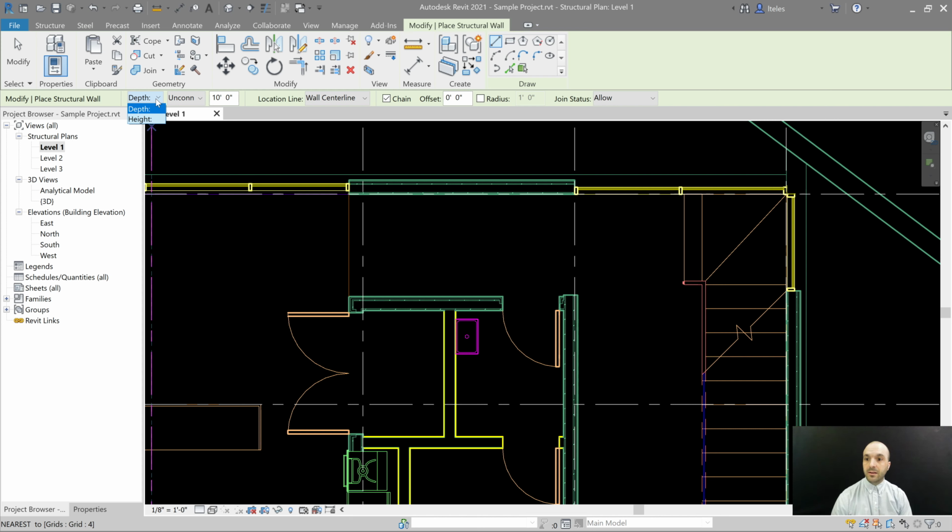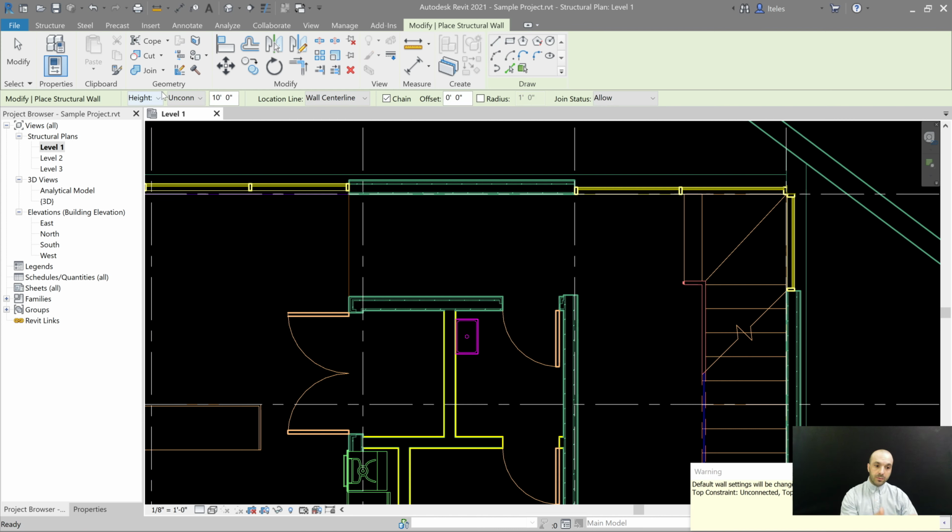Fight the habit of not going through these options, okay? So let's go through these and tell Revit, we're communicating with Revit and saying, no, we want it to go up. Revit tells you got to reset and keep going with your options. And the next option over, we tell Revit, we want the top of this wall to go to level 2.